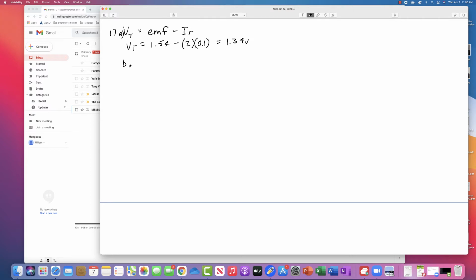Now, what happens to that internal stuff? Well, this voltage is what produces power, and it asks the question, what is the power? This is the total power that's produced, and this is the actual realized power. So the total power produced is equal to this total available EMF times the current, which is going to be 3.08 watts.